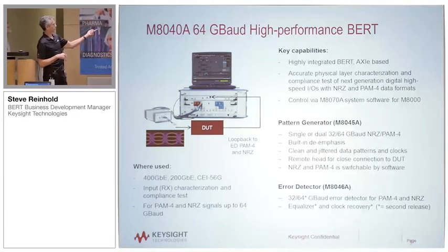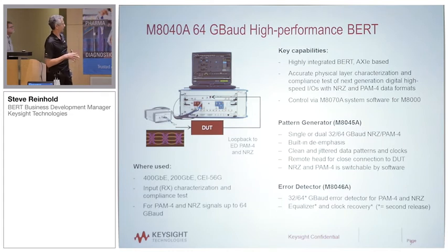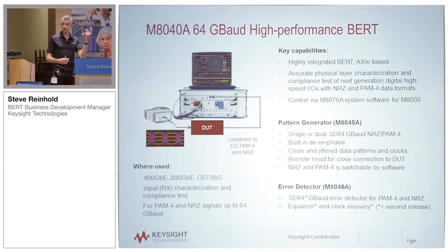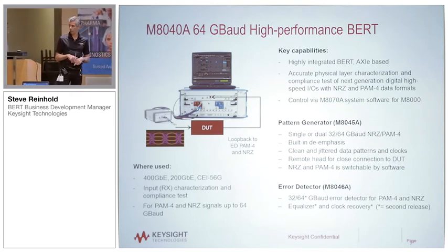The error detector is a single slot module that's above the pattern generator, which is a 3-slot blade. Again, it's a native PAM4 and NRZ error detector, so you don't have to split the signals into multiple NRZ detectors. And we're working on equalization and clock recovery for that.